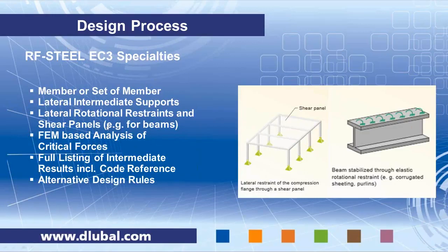Also, it is important that you have a good, stable numerical solution for your critical forces, namely the critical axial force and the critical bending moment. In the code, there are simple analytical formulas, or mainly in the national annexes, with parameters C1, C2, C3. Those are derived from a simple fork-supported one-way beam.